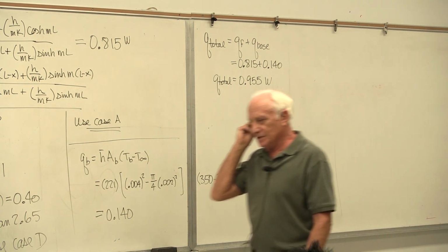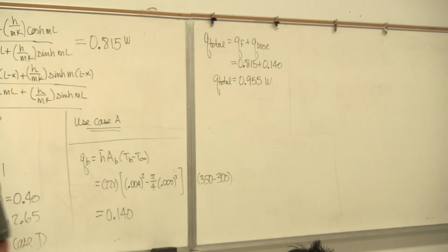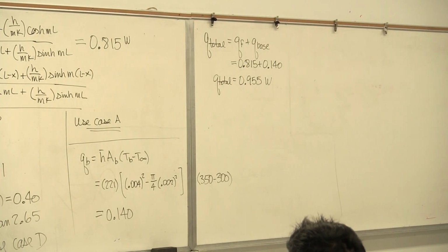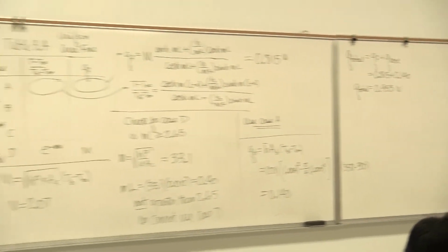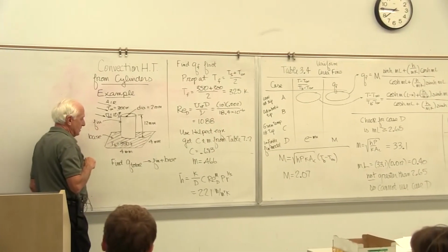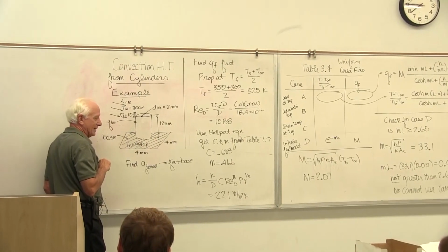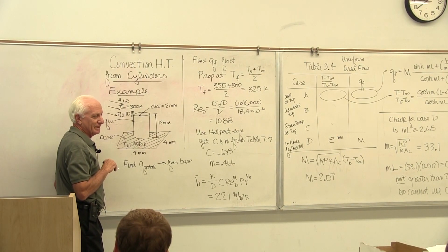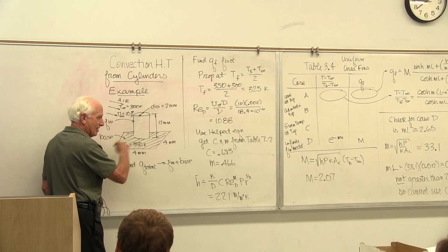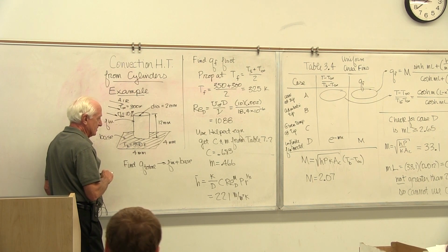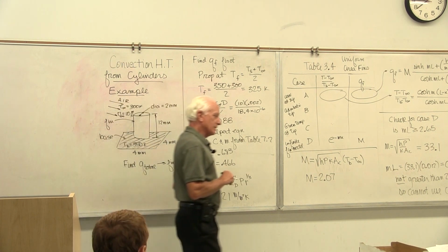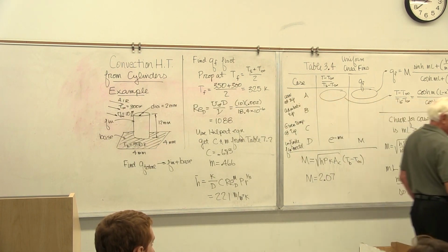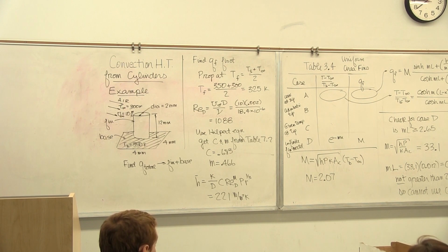Yeah, we're assuming the H didn't change. Of course, that's suspicious. I'm sure it does, because this plate is not getting the full impact of the air. So maybe you want to use the first part of Chapter 7, flat plates. We wouldn't get that sophisticated in this class, but that's what you probably want to look at. These fins would be mounted on a flat plate. Try and get some estimate of what that H-bar might be over a flat plate with fins attached to it. It's not an easy calc. We will assume it's the same, though, in this class, okay?